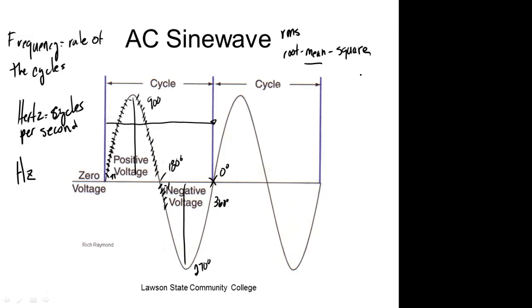Now for a sine wave, it always comes up to be V peak times 0.707. So you get 70.7%, and that's what your meter measures. So your meter measures RMS. Most of your cheaper meters just divide it by 0.707.